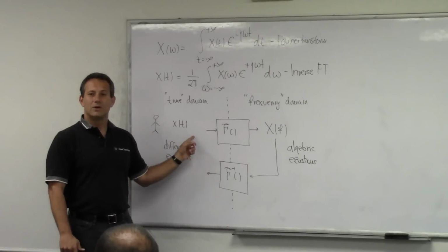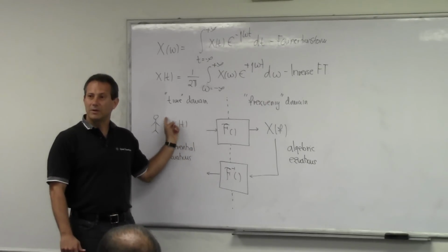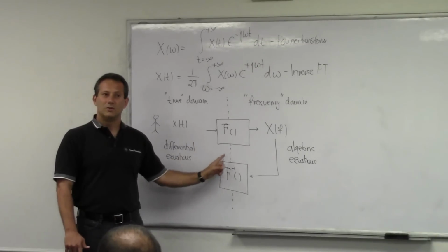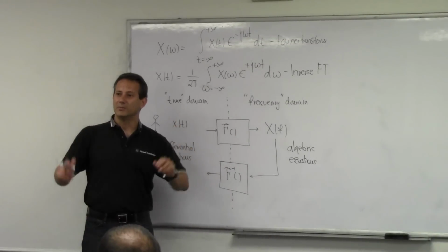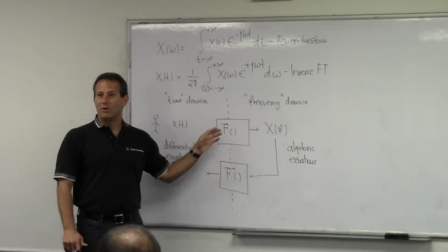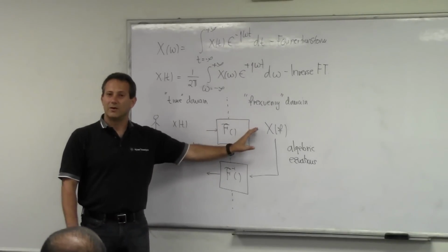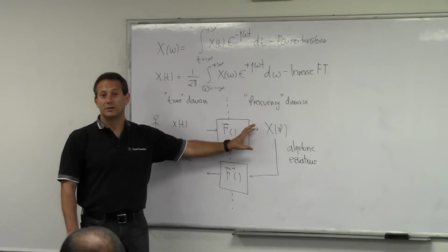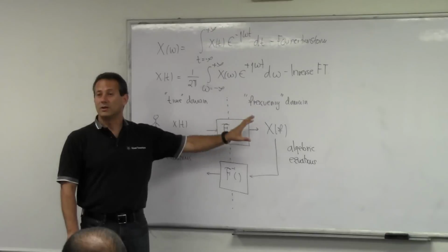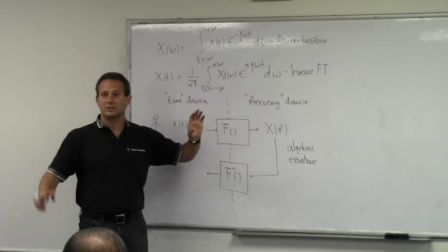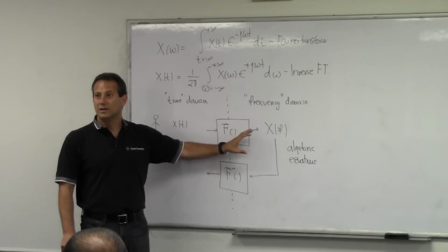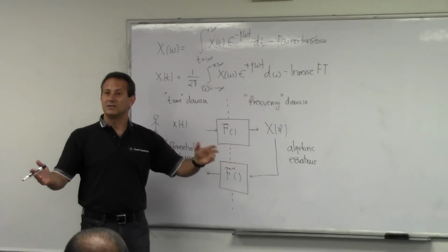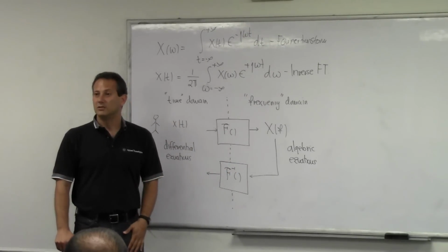But if you take these equations that are happening in the time domain, and you apply the Fourier analysis, you end up in what we call the J omega domain, right? Where all of your circuits, now AC circuits, can be solved using an algebraic approach, right? So we know that the capacitor has this new impedance, 1 over J omega C, and J omega L for the inductor. All our equations, we write them as if we were in a DC domain.